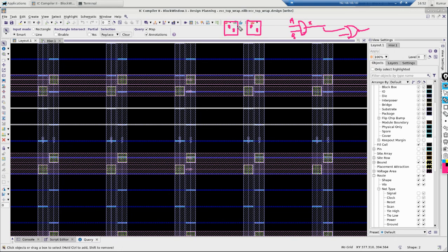So now these cells will come and sit in between these rails. So they get powered by sitting here. They just get hooked to the power when they sit here. Okay, so this is something that we call power routing. So the whole structure that you see here, the stripes and the rails, and you connecting the stripes and rails through something called stack via.